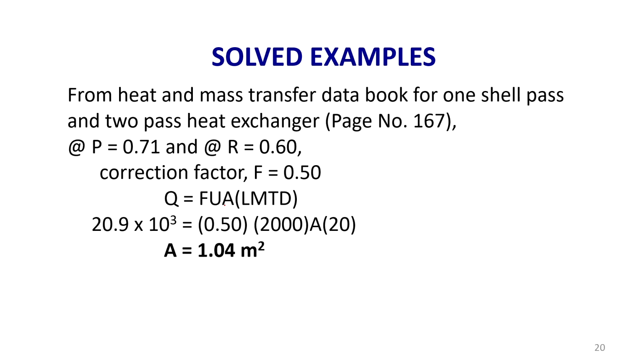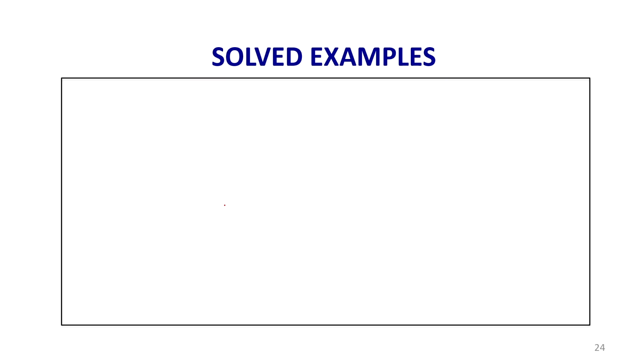The rate of heat transfer is like this: suppose it is a shell and tube, first there is convection from the fluid in the shell portion to the tube. Then within the tube, that is conduction. Then again from the tube to the fluid, it will be convection. So, it is convection, conduction and convection. This is quite a lengthy problem, so let us use the data book.